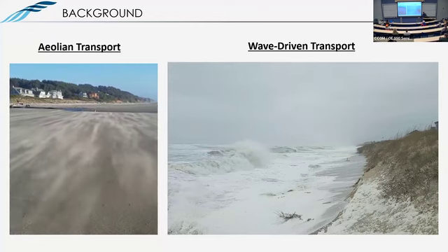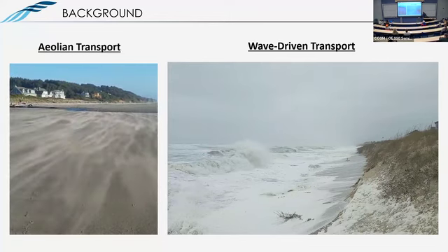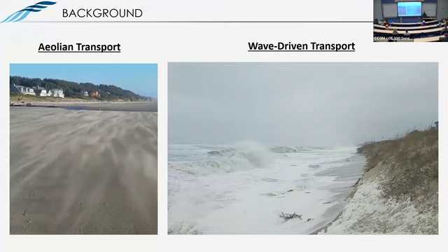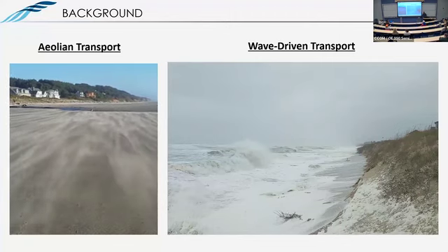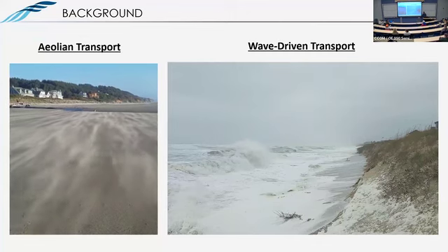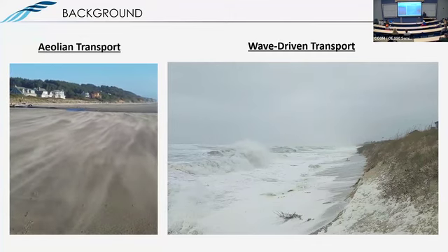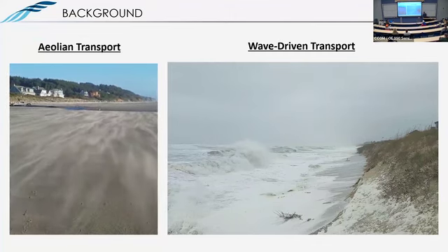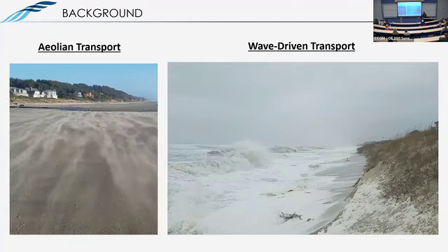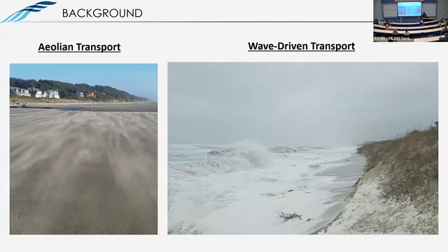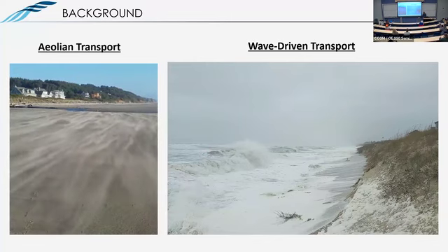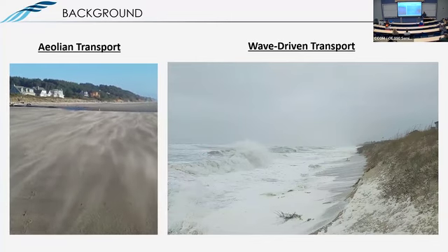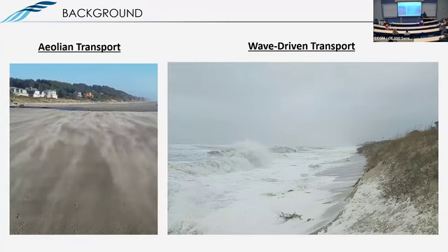No, for sure not. When coding these models, you just add a new way of doing that. So you could add the Bruun rule in there too. Well, not just the Bruun rule, but something maybe more predictive and process-based. And if you had considerable offshore transport or wave angles, you could link it with a shoreline change model, which would probably be the better way of doing that if your shoreline changes are driven by sediment losses down the coast.